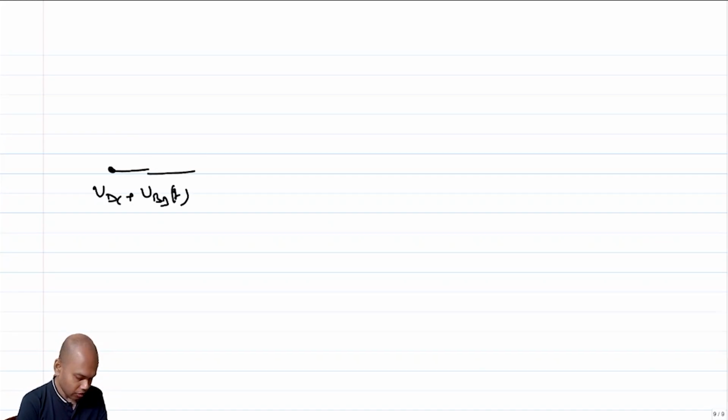And we saw it in the receiver cases also. You go to an active mixer, right? What is an active mixer? Instead of driving through a voltage source and then switching, you drive through a current source, right? So what I mean is, let's say you have an IDAC. Or rather, I'll start from VBB. Let's say you have VDC plus VBB. You pass it through a common source amplifier.